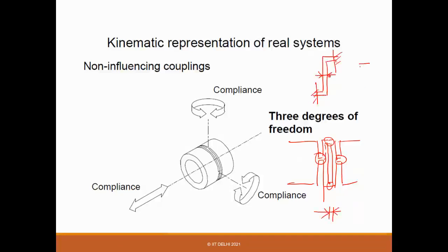So it can bend like this, and it provides you this translation also. So now it has 3 degrees of freedom: 2 rotations and also this translation. Of course, these are limited. What we are talking about are very small deformations.